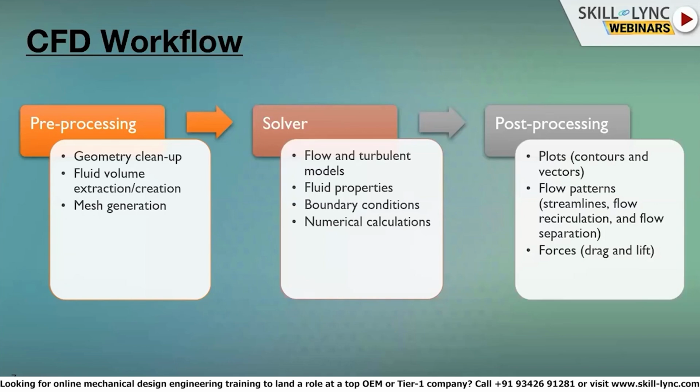In that, he has to select the right flow models, whether it is laminar or turbulent, and fluid, define the fluid properties, then numerical methods, boundary conditions, convergence criteria, the parameters which he needs to monitor for the convergence, etc. And obviously running the solution.